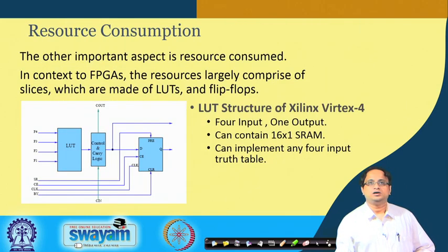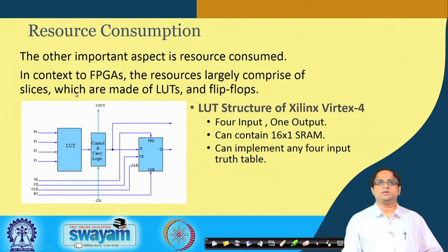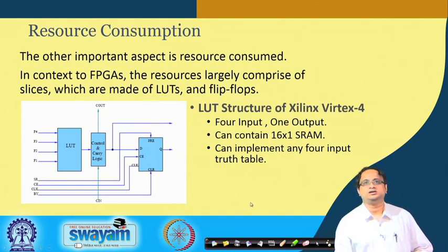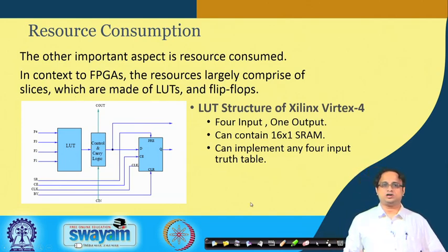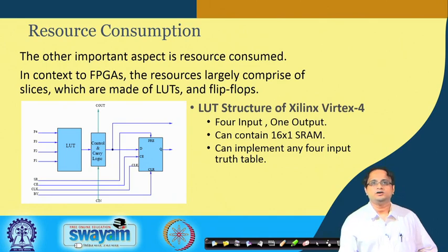Now, when you want to make a design, the other important thing is the resource consumed, because you also want to make your design more compact. So, let us take a look back at our structure of the LUT. This is the structure of the LUT for Xilinx Virtex 4, where the LUT has got 4 inputs. So, it is basically realizing any 4-bit Boolean function.